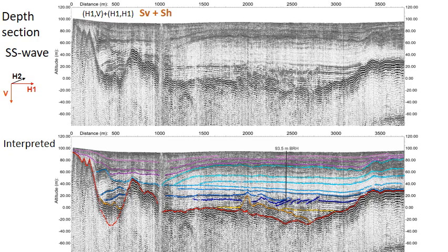Based on our seismic facies analysis, we predicted that an aquifer would be met at a depth of 95 meters. The borehole drilling was stopped at a depth of 93.5 meters as some water was starting to flow up the well, and the drilling equipment was not set for handling an artesian high-pressure flow.